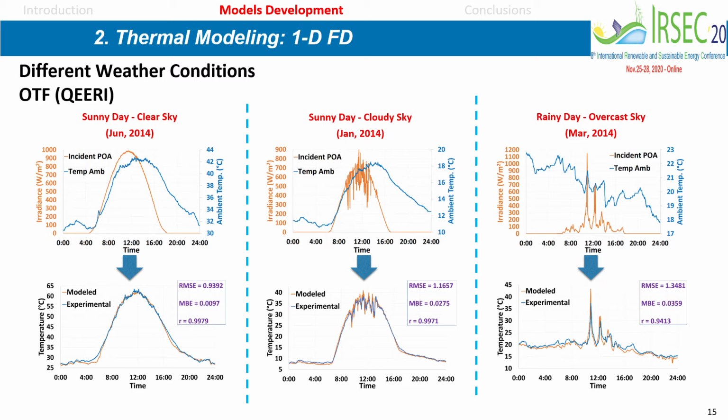one-dimensional model is sufficient. However, it all depends on what you need. If you need to have an accurate distribution of temperature throughout the panel, in 2-dimensional or 3-dimensional, you have to go to 2-dimensional, 3-dimensional, and I will show you that 2-dimensional is probably enough. Okay, but 1-dimensional, it all depends on the application. If I'm just looking for temperature, 1-dimensional is more than enough.